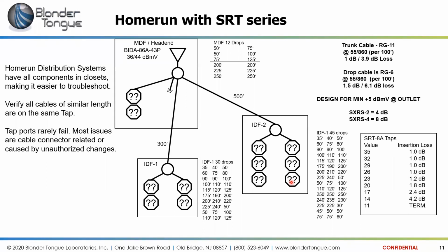Okay. We're hoping to get an answer to ideal input window for a BIDA 550-50. Well, if you go with the math that I've mentioned on the 30 and the 43 dB amps, again, the BIDA 550-50 also has a rated output of 36 dBmV on the low side and 44 dBmV on the high. So 44 dBmV output minus 50 dB of gain puts our input level at a -6 dBmV minimum on the input. That amp is rated for a -6 to about a -4 on the input.